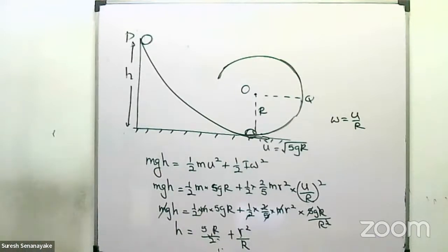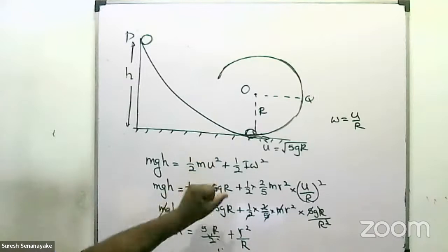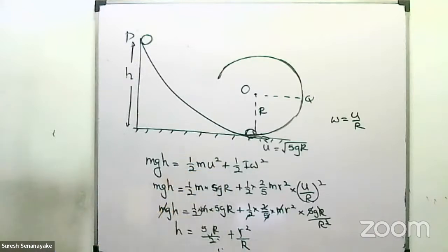You force this down vertically, but there is no torque about the axis. If the moment of inertia decreases, then angular velocity increases. So the rotational kinetic energy increases. That increase in rotational kinetic energy, the difference of the rotational kinetic energy before and after, should be equal to the work done to force the collar down.